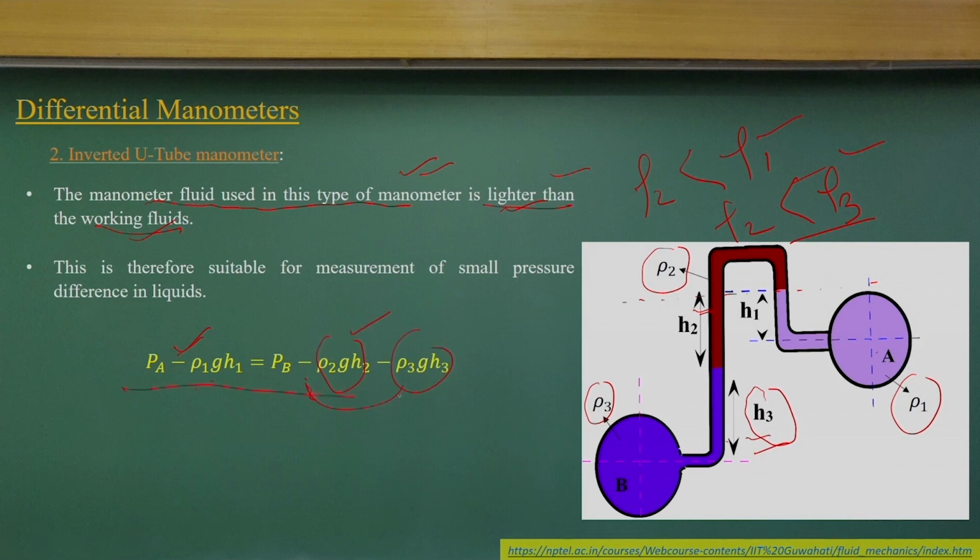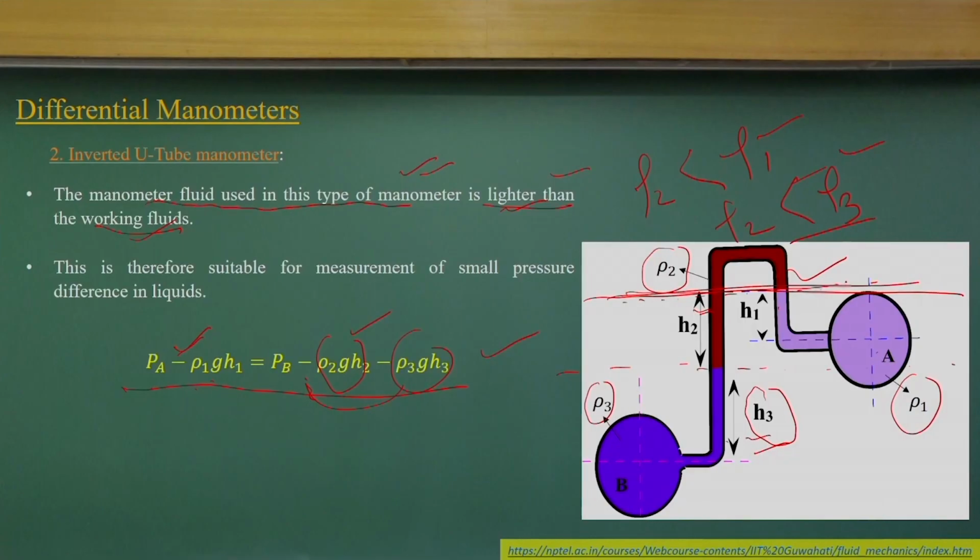So, you can write these pressure equations for an inverted U-tube manometer, considering this is the surface where you equate the pressure. You can consider any other location, that does not matter, only you have to follow a sign convention, whether the positive and negative sign of h you consider, to solve the problems. You can know which one will give a simplified case, like the surface you consider.